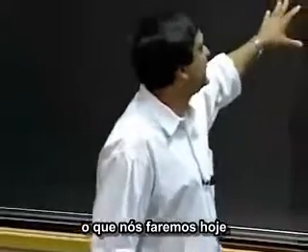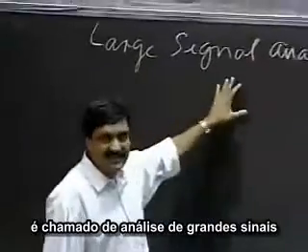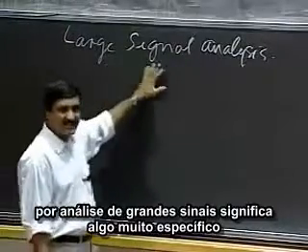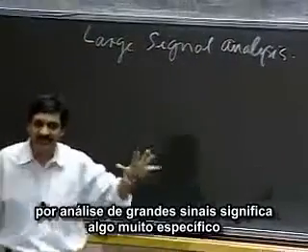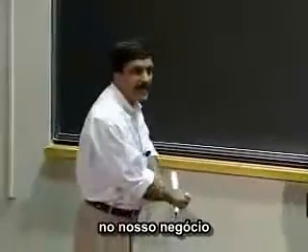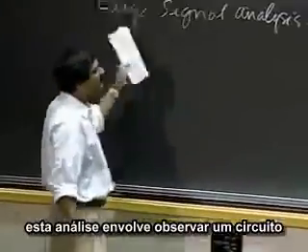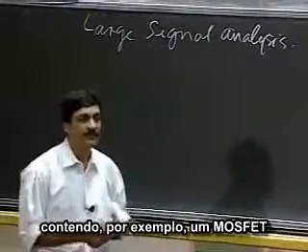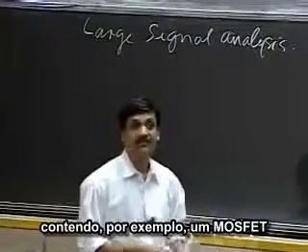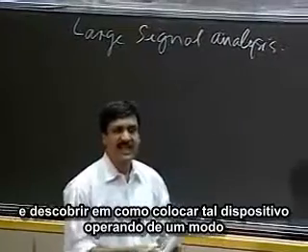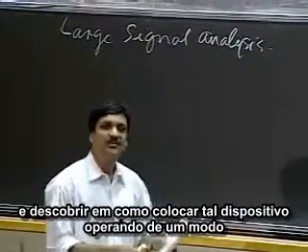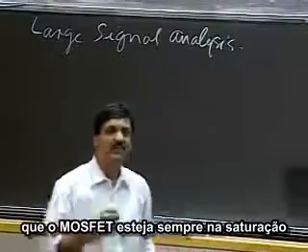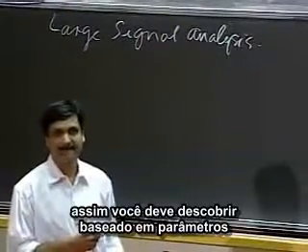What we're going to do today is called large signal analysis. And this is a loaded term. Large signal analysis means something very specific in our business, and I'll describe to you what that is. This analysis involves looking at a circuit containing, for example, a Mosfet, and figuring out how to get that device to operate in a way that the Mosfet was always in saturation.